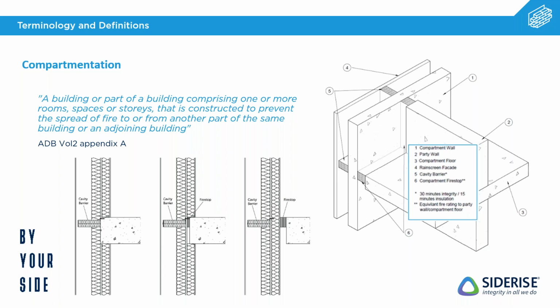So even though with masonry application, where we have quite specifically an inner leaf, which is forming the difference between obviously inside and outside the building, because we have a cavity between that inner leaf and that masonry, that could form a space that could allow for the spread of fire and smoke. So we need to protect at compartment lines wherever we have those cavities spanning them.